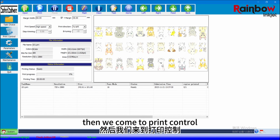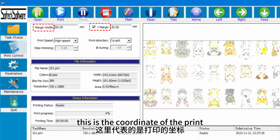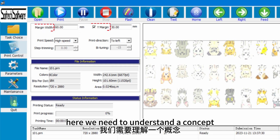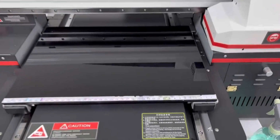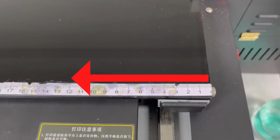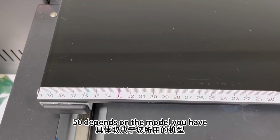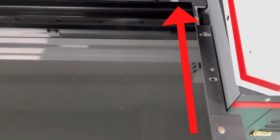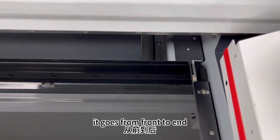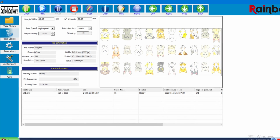Then we come to print control, margin width and Y margin. This is the coordinate of the print. Here we need to understand a concept, which is the x-axis and y-axis. This is the x-axis. It goes from right to left, from 0 to the end of the flatbed, which could be 40, 50, depends on the model you have. This is the y-axis. It goes from front to end. And note, this is in millimeter, not inch.